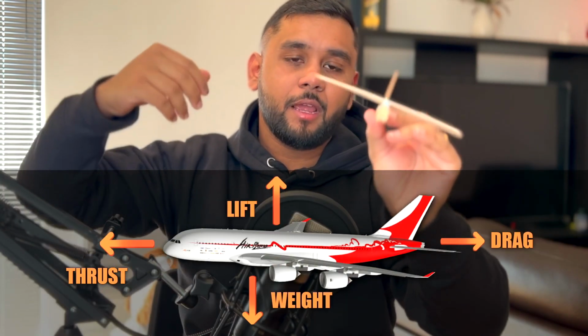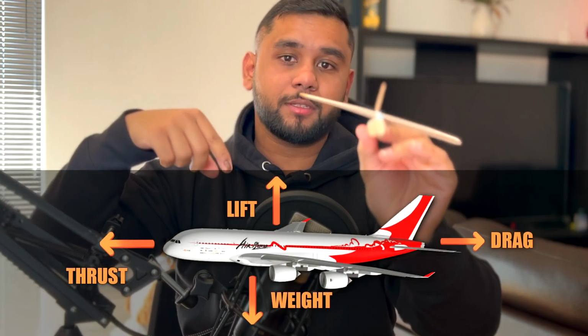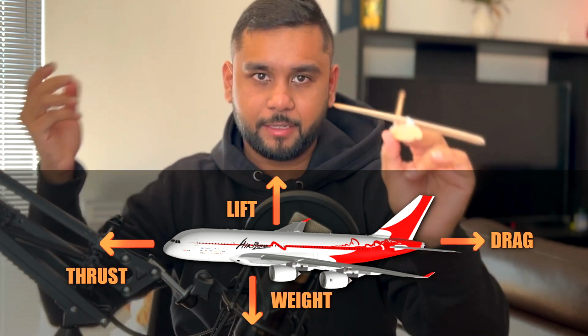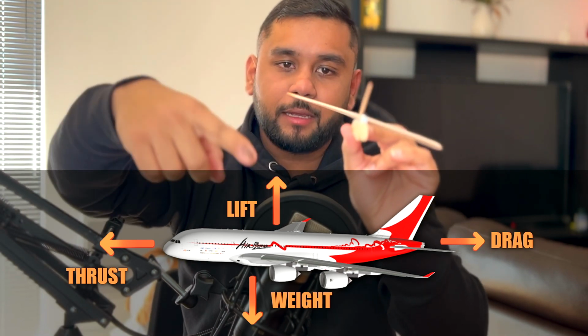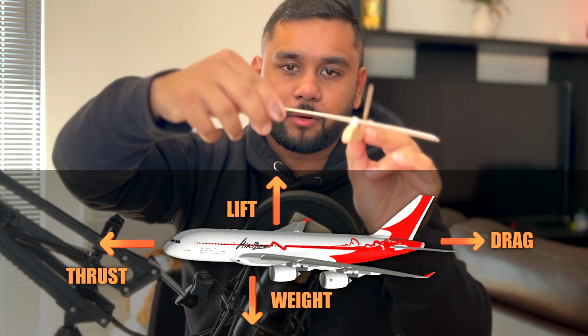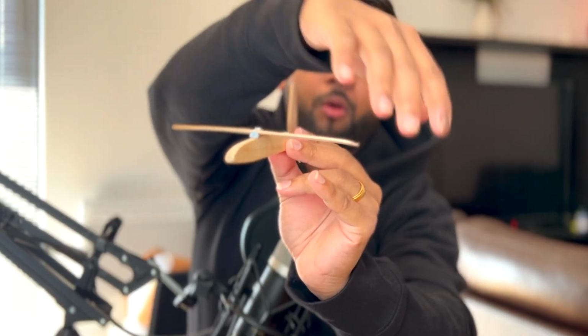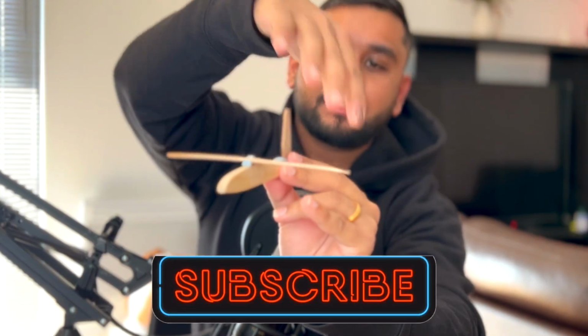Now the aircraft is like this and there's high pressure building below this wing, causing it to lift up. And with the lift, there is something that increases, and that is drag. Drag is the resistance force that opposes the movement of the aircraft. If the aircraft is moving forward, drag tries to push it back. Easy. So now when more lift is created here, high drag is created here, so the aircraft turns like this and the nose will go towards the right. When the nose goes towards the right, the aircraft is in a position like this. Now what happened is there's more exposure on this side of the vertical stabilizer.